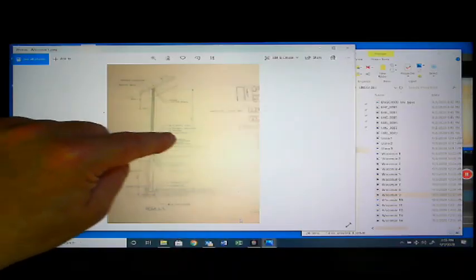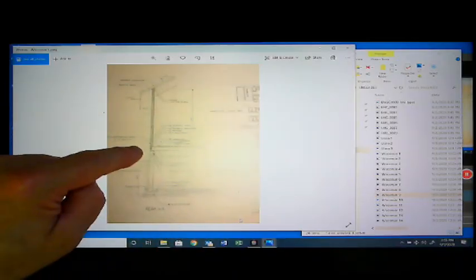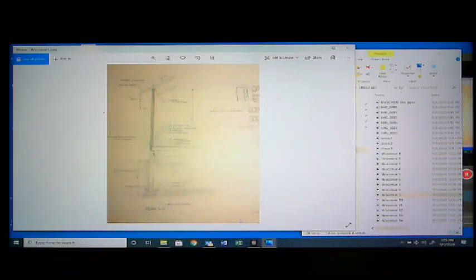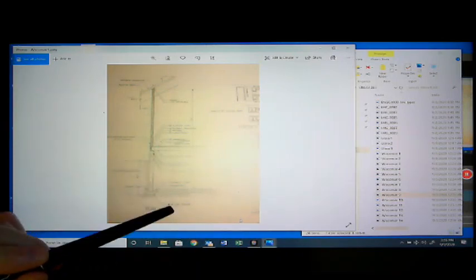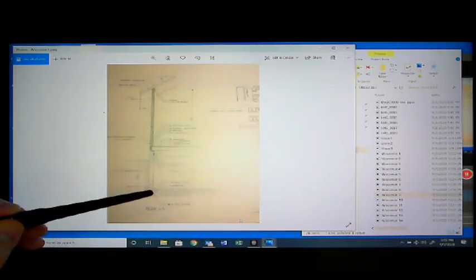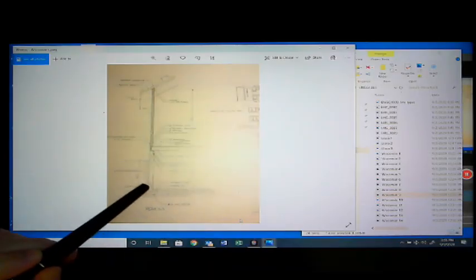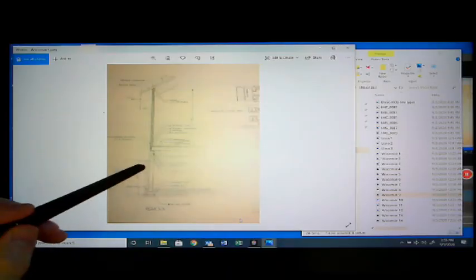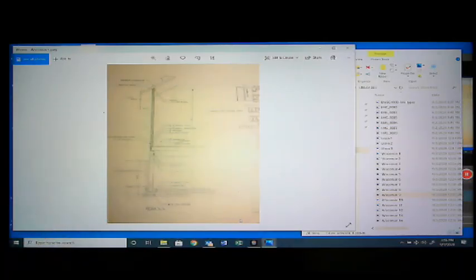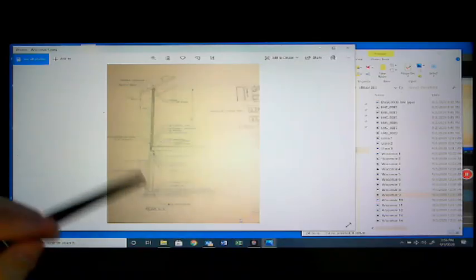All of the parts that go into making up that wall are listed. Here it shows the detail of, here's the floor joist coming in and everything laid out so that whoever builds this doesn't have room to be creative. And you'll notice just all the details in here. So we have how it is to be filled up to putting in this concrete floor. Here's the foundation wall. Notice there's a little indentation down here. It's a key lock so that you don't want this thing to just slip off. With all the ground here, it wouldn't slip this way. If you don't have that key, this wall literally could, over time, slide off the foundation and collapse. That keeps it in. So all the little details shown.